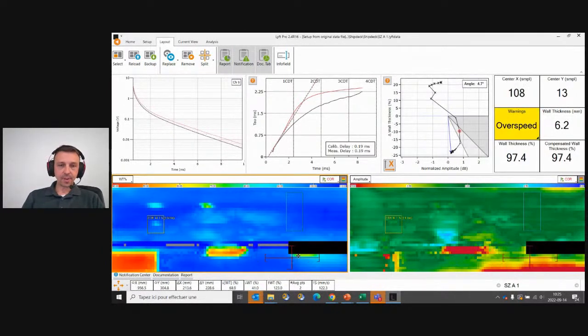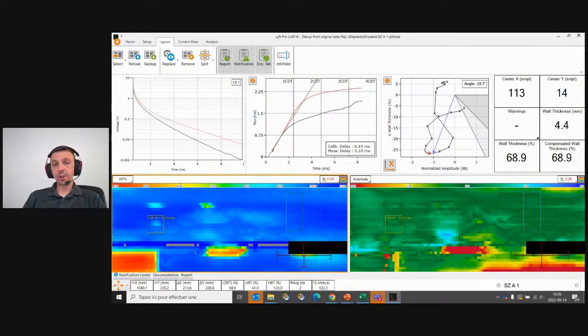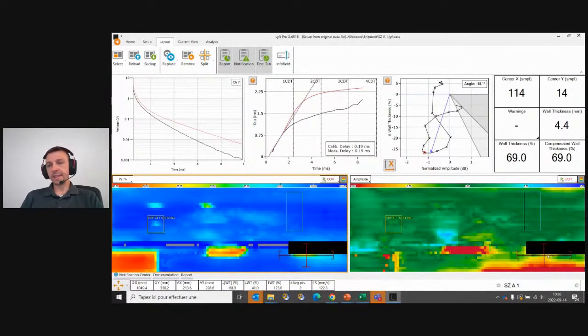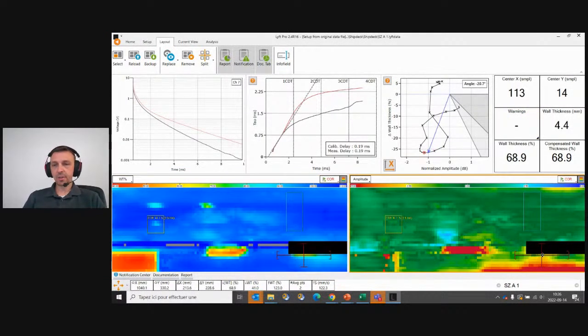The last defect is located close to the pipe. This is why we have a zone where we don't have any data. We did not have access with the probe, which happens quite often for a ship deck inspection because they have a lot of interfering components. In that case, we are sizing close to 68%. This area is also larger than the averaging area, and we have a good sizing. And as we can see on the amplitude view, this defect did not seem to contain any false positive indication, or it was not affected by the manufacturing process.